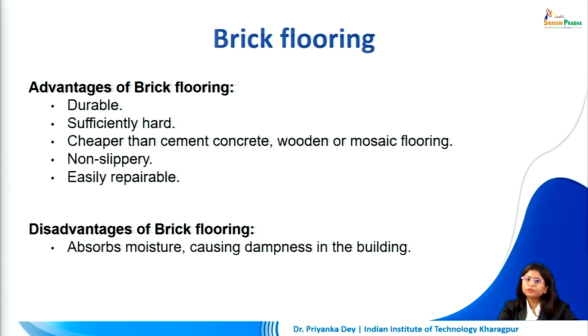The advantages of using brick flooring is that they are sufficiently durable and hard. They are cheaper than cement, concrete, wooden or mosaic flooring. They are definitely non-slippery and they are easily repairable, because we can easily do spot repairs if 1 or 2 of our bricks are damaged. The disadvantage, however, is that it absorbs moisture and it causes dampness in the building.